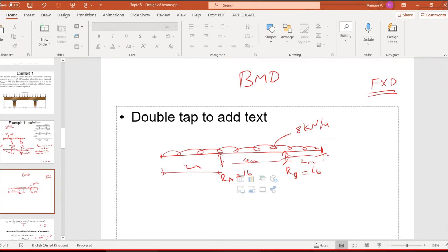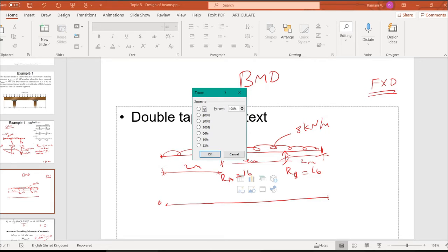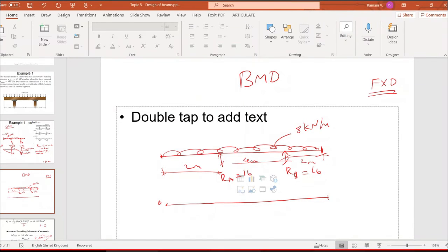Just use the same color, same marking. And because it is a free end, right? Free end, you still have the 0 value here, right? At this point is 0 value. No force, no moment, right? Because when force becomes 0, whatever the distance you have, the moment is also 0, so we end up with 0 value at this end.